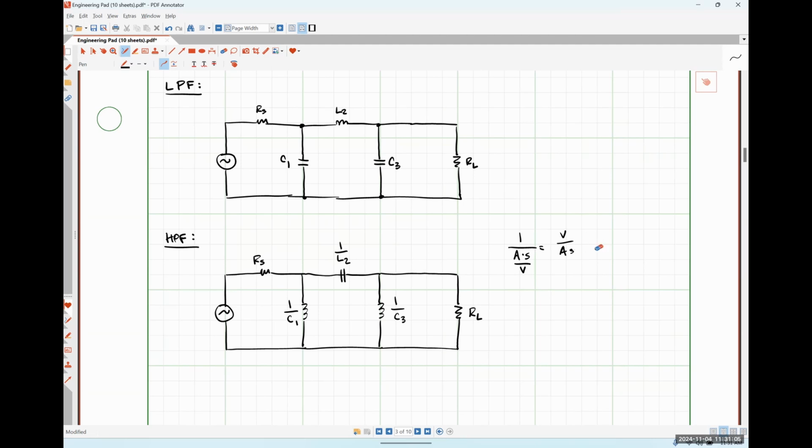The volt per amp thing, like if we would have had a second up here, that's going to be the exact same thing as a Henry, effectively. So by just using the reciprocals of the units, it comes out to be the correct thing as well, okay? So low pass filter and high pass filter, pretty straightforward. We simply swap our elements around and then take the reciprocals, okay?